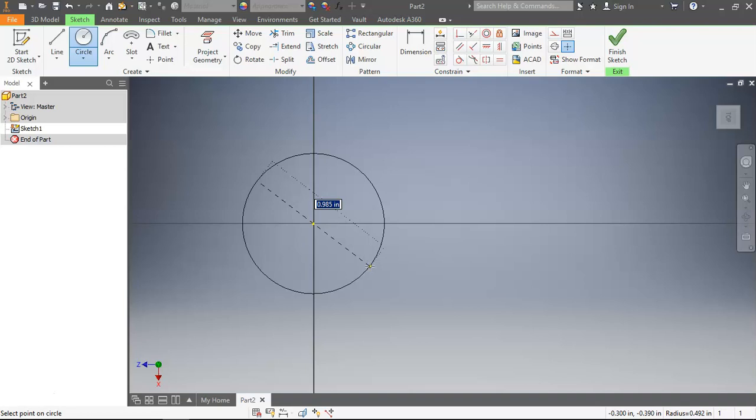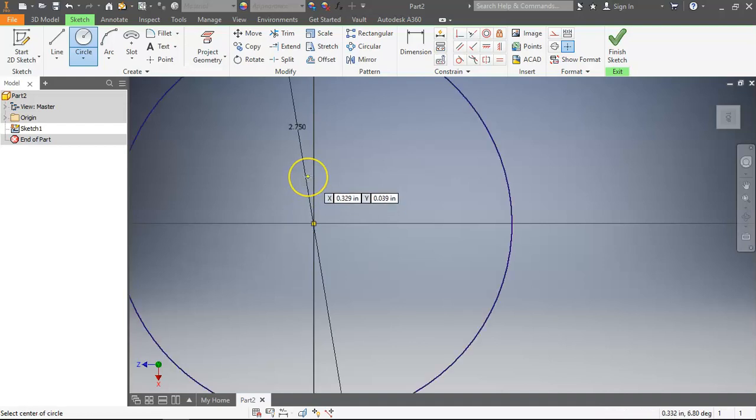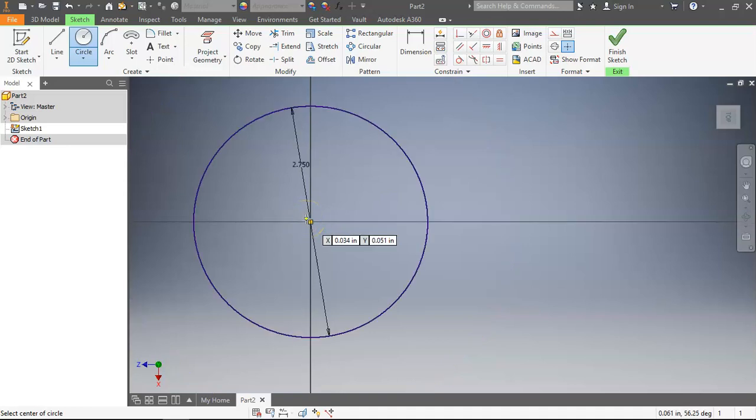So in order to figure out what the diameter is, you're going to have to multiply things by 2. And if you don't want to multiply it by 2, remember that where you type in the dimension is also a calculator. So, for example, this circle right here has a radius of 1 3/8. If I want to make that a diameter, I could just make that 2 6/8. If that doesn't jump out to you, I could say 2 times, parentheses, 1 plus 3/8. What that's saying is the 1 plus 3/8 is 1.375, which is the radius, and then multiplying that by 2. And 2 6/8 would be 2.75. Just showing you different ways of doing it.